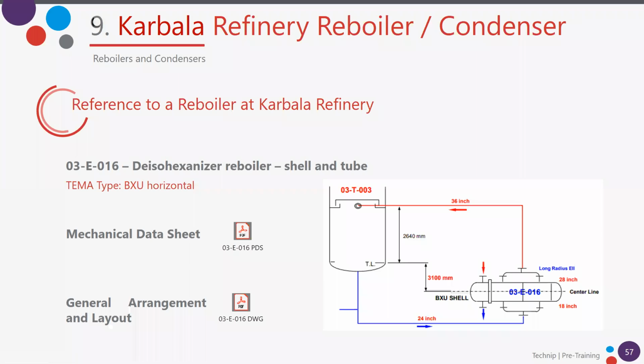We've got just one question here. The question says more likely fouling fluid should be located on the tube side. This is the rule, yeah? So why for this reboiler is the rule reversed? They put the more fouling fluid on the shell side.